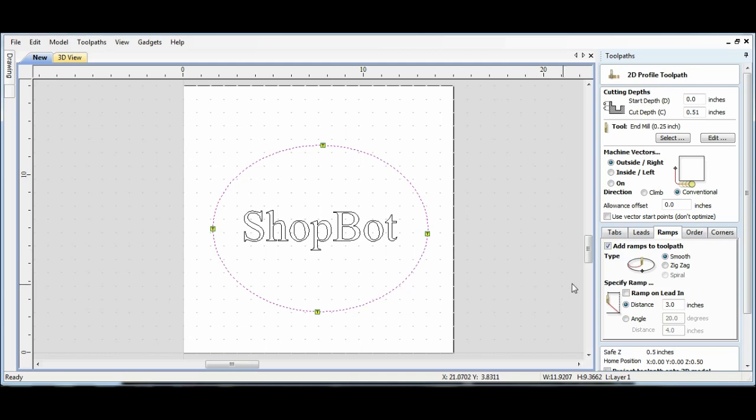And once again, it sounds silly, but it really does help out. So it doesn't hurt anything. It might be adding seconds to your toolpath time, but in the long run, it'll make your bits last longer. It'll make your X, Y, Z coordinates not jump out of whack if you're removing too much wood. So I definitely recommend it, and it's very easy. Just leave it. You don't have to mess with any of these settings. Just leave it all.